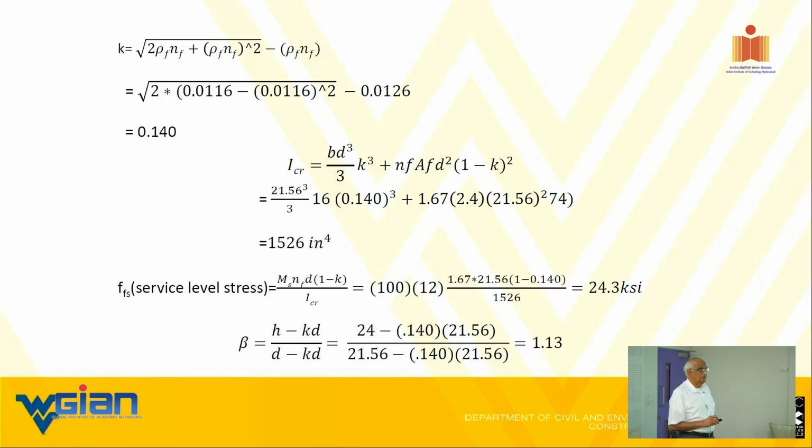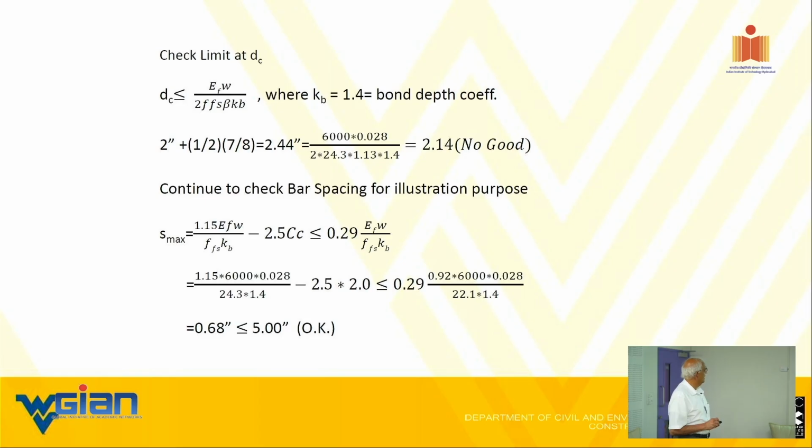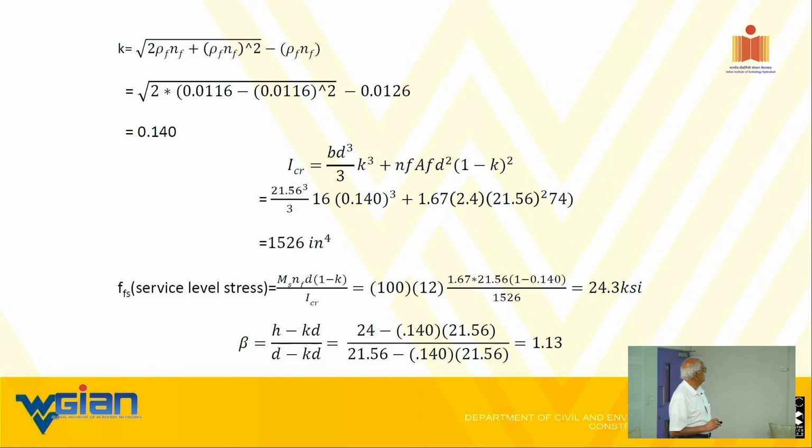This is typically about 1/10 or 1/12 of your I gross value. I don't know that I have that here readily available or not, but that's about what it is. So you can kind of figure it out, 1/12 b d cube, so that'll give you whatever the number you're looking for.